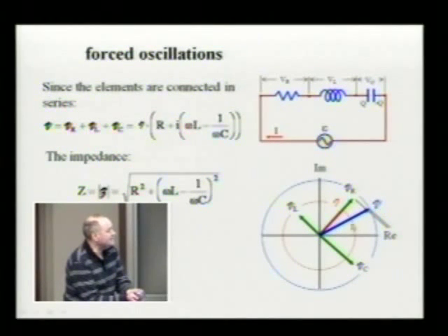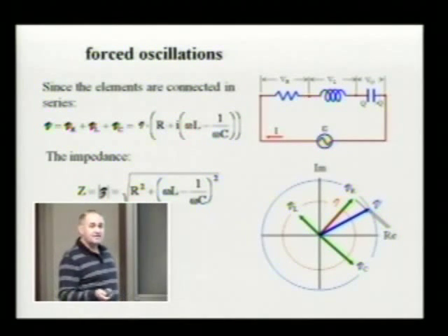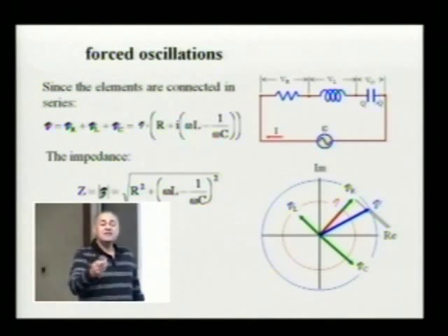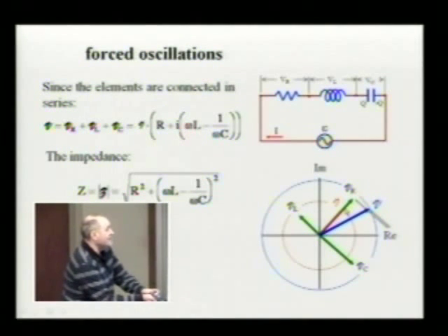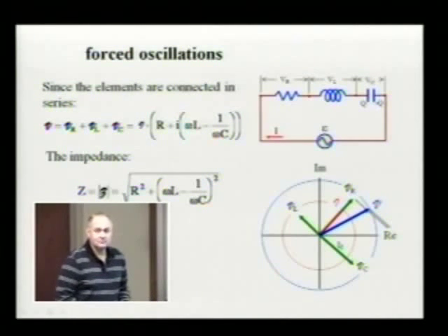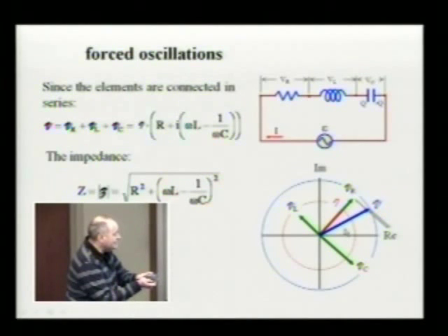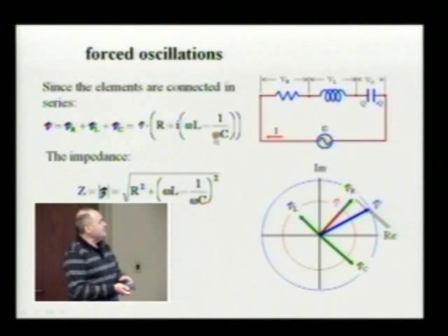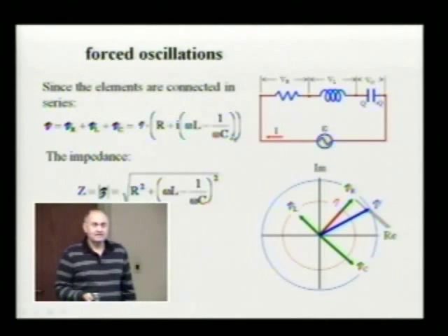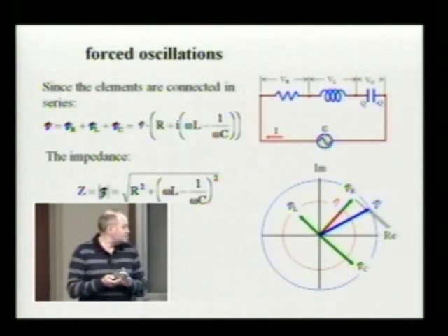All right, how do we find the phase angle directly from the complex impedance? Andrew, do you remember that? The tangent of the phase angle is equal to the imaginary part of the complex impedance divided by the real part of the complex impedance. Now, what is the imaginary part of the complex impedance over here? Can you identify that? Omega, or whatever is after the i. Yes, so this is the imaginary part of the complex impedance. I have it here. And the real part is the resistance.